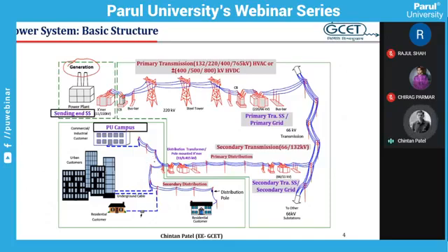And as the current is high, its immediate effect is IR and I square R. The IR is the voltage drop in the transmission conductors, and I square R is the power loss. So as the current is high, the IR drop and I square R loss will be very, very high. This will reduce the efficiency of the transmission network, and there are many problems associated with this. So to decrease the current, the voltage must be increased. This is done with the help of a generating transformer at the power plant.